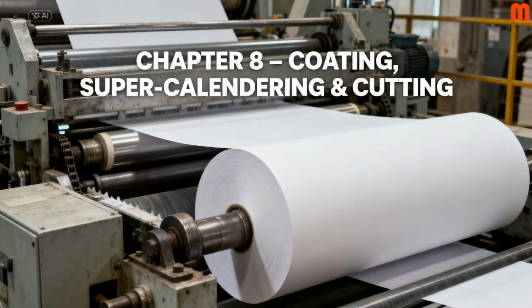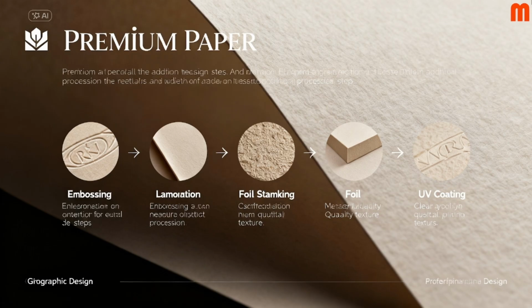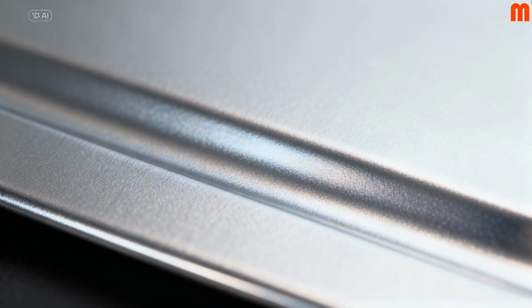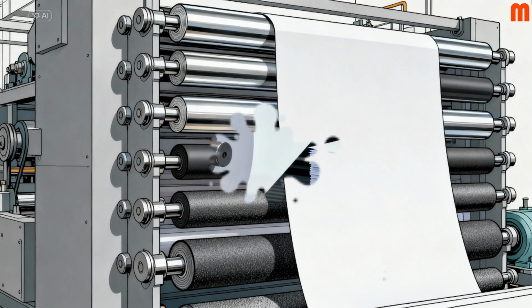Chapter 8. Coating, supercalendering, and cutting. For premium papers, additional processing steps are applied. Coating. Special coatings polish the surface and increase brightness or softness. Supercalendering. Paper passes through a stack of alternating hard and soft rollers, sometimes up to 18 rolls. This produces extremely high gloss, magazine quality finishes.